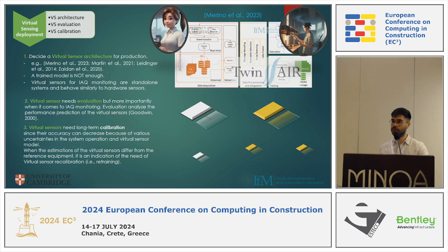You need to build this into a system that behaves directly like any other hardware sensor. So if anyone comes in and sees the data, they wouldn't even notice if it's a virtual or a hardware sensor. And for that, there's some literature that tackles this and creates an architecture for using virtual sensors seamlessly. You need evaluation of these sensors and also long-term calibrations, because again we need to think about them like any other hardware sensor, and basically you can use other hardware sensors in the space as a reference for this calibration.